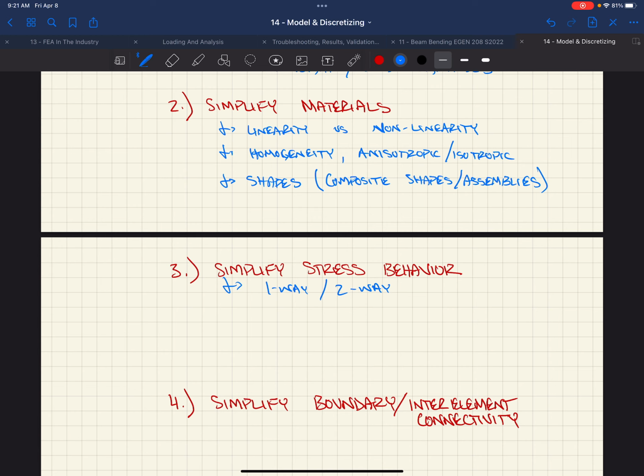So looking at two-way action versus one-way action for concrete slabs, right? We make some pretty bold assumptions with respect to that, especially when we get close to that 2-to-1 ratio, where we start changing that performance. If I was on a one-way slab, but I was standing really close to the end of that one-way slab, the chances are it's going to act two-way, right?